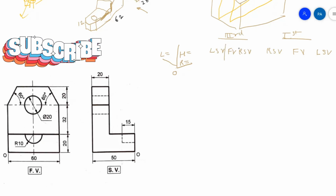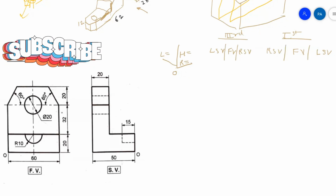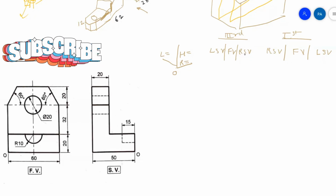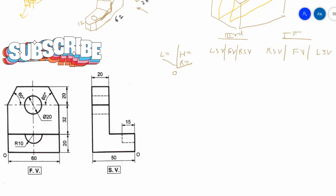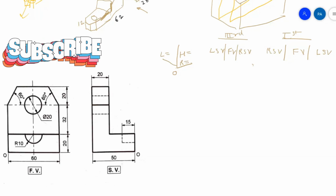Now, how will we understand whether this is first angle method or third angle method? That is important to understand, because otherwise it could be the right hand side view and we will consider it as the left hand side view, and we will get something different. We will get a different object. Now, in this present sum, you can see that this is a symmetric object.